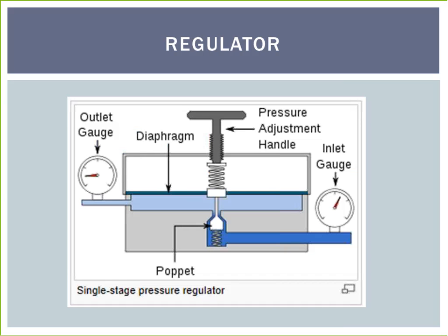A pressure regulator's primary function is to match the flow of gas through the regulator to the demand for gas placed upon the system. If the load flow decreases, then the regulator flow must decrease as well. If the load flow increases, then the regulator flow must increase in order to keep the controlled pressure from decreasing due to a shortage of gas in the pressure system.